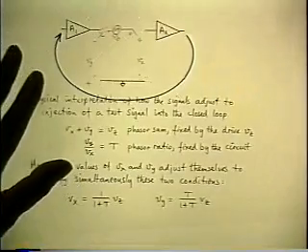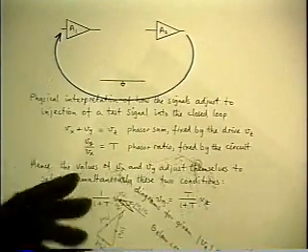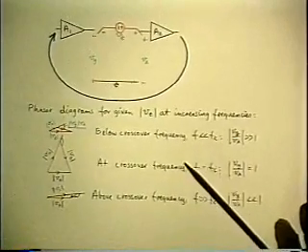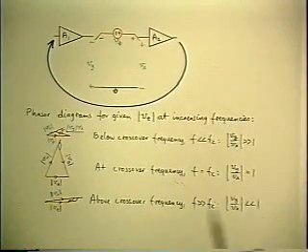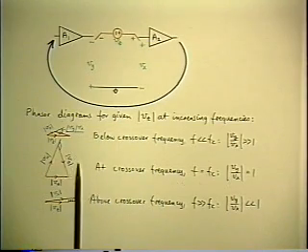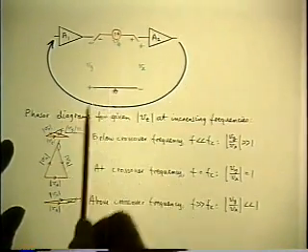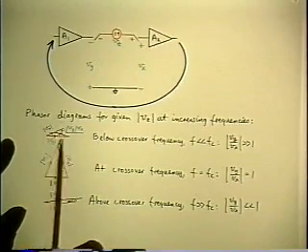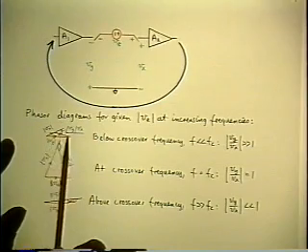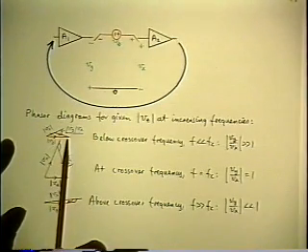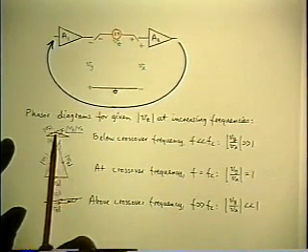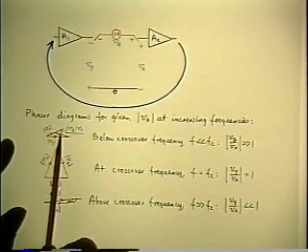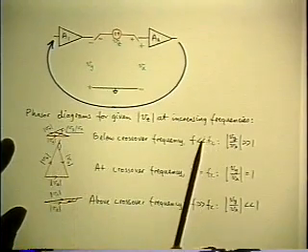It may help also to draw the phasor triangle for a few cases, just to see what its configuration is. Suppose you draw the phasor triangle at a low frequency when the loop gain is large. Vz is the independent quantity, so I put that in the reference direction, and it has a fixed length. And the rest of the triangle is formed by a small Vx and a large Vy with a small angle between them, because that's what you get at low frequencies.